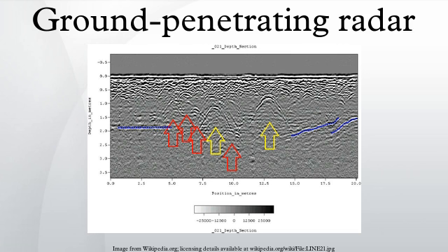This holographic subsurface radar differs from other GPR types in that it records plan view subsurface holograms. Depth penetration of this kind of radar is rather small, but lateral resolution is enough to discriminate different types of landmines in the soil, or cavities, defects, bugging devices, or other hidden objects in walls, floors, and structural elements. GPR is used on vehicles for close and high-speed road survey and landmine detection as well as in standoff mode.